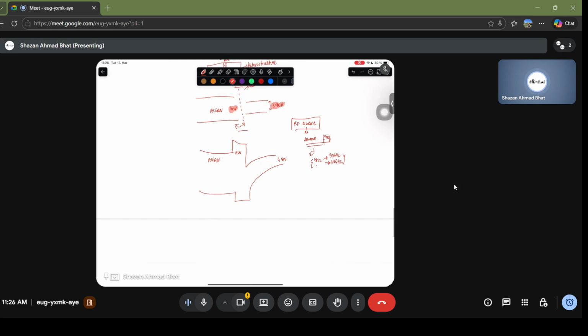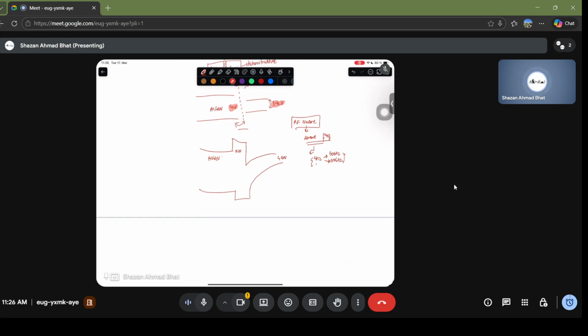Okay. And what essentially happens here is that at this particular position, you have the Fermi level crossing the conduction band of it. And this forms a triangular potential for an electron. So this is a triangular potential for the electron. And because of it, the electron's energy levels are confined here. So you no longer have a continuous energy, but you have a confined energy, and that gives rise to something called the electron wave function. And it looks something like this.